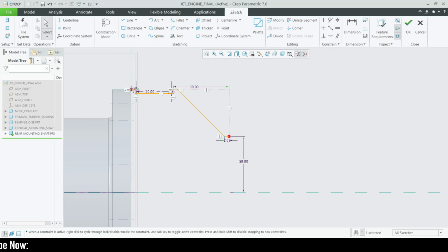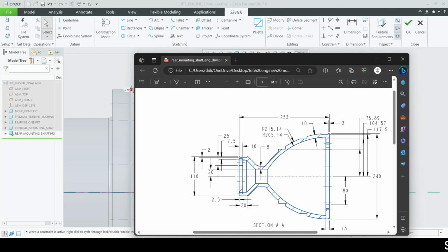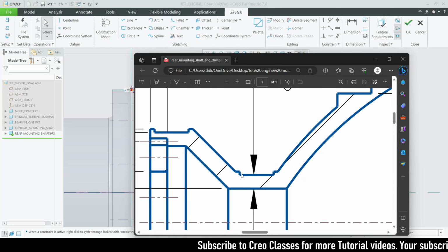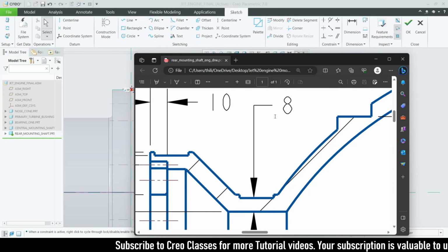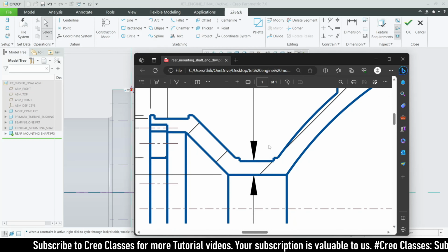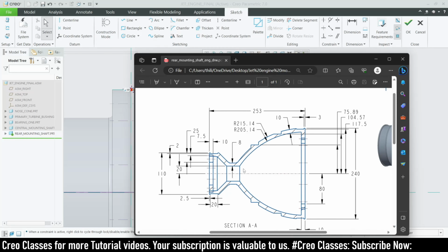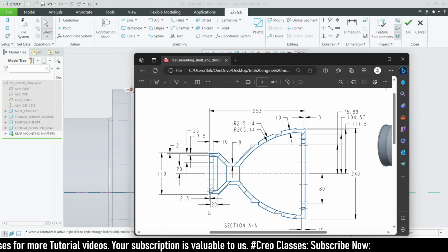Let's go for the sketch again. We need to create this drop feature. As I said before, this total height will be 10, so from this 10 we have to minus this 8. So it will be this extruded value. When we zoom here, you can see this value will be 2, 10 minus 8. And we need to know this length, which will be same as this, so it will be 20.